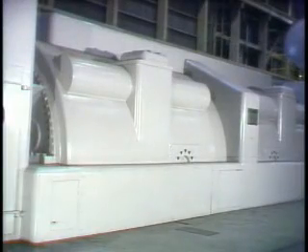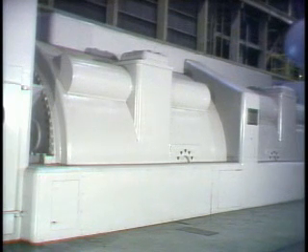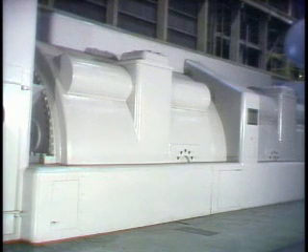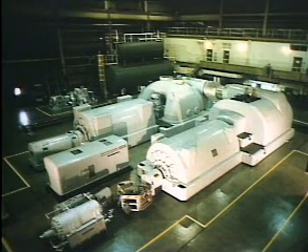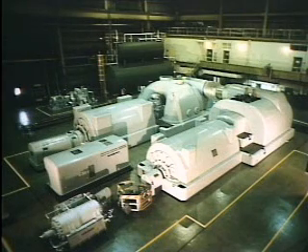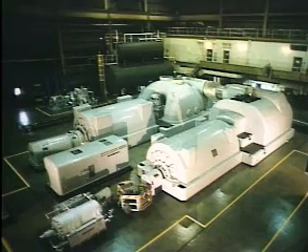Hydrogen is capable of absorbing about 7 times more heat than an equal amount of air. This means that a generator can be cooled more efficiently with hydrogen than it can with air. Another advantage is that a large hydrogen-cooled generator can be housed in a smaller casing than a similarly rated air-cooled generator, so less space is required.